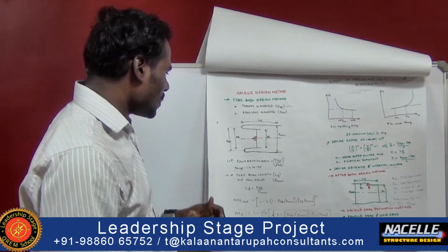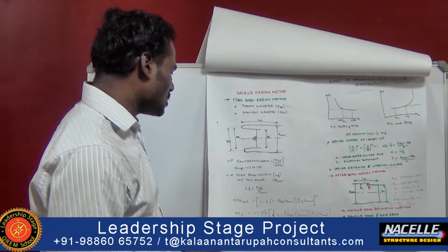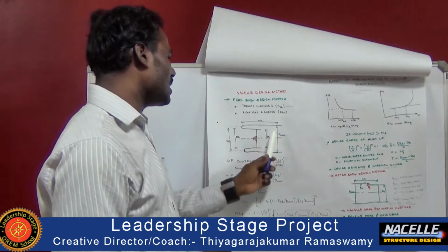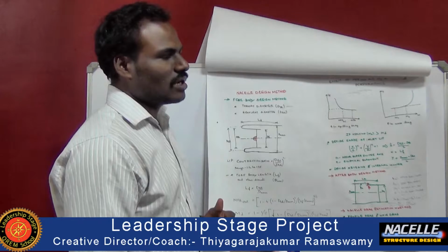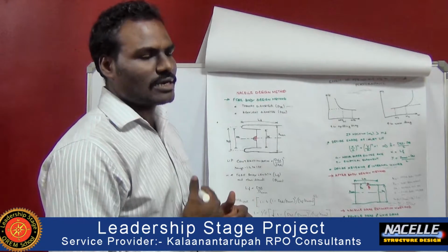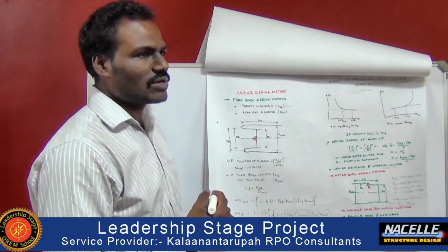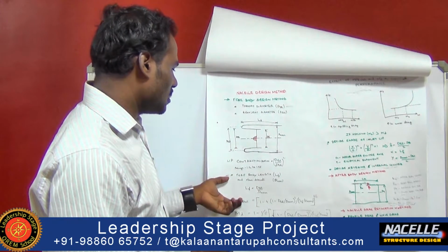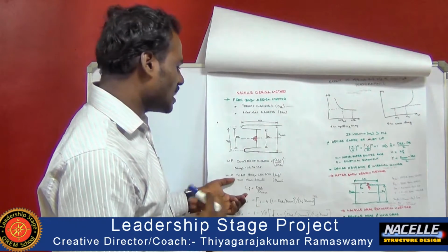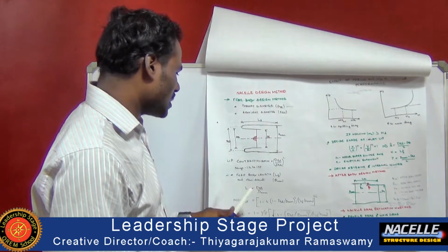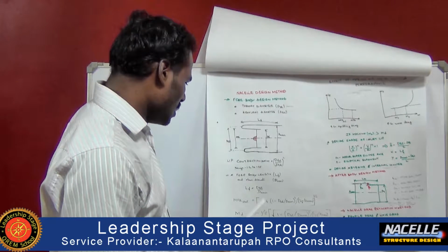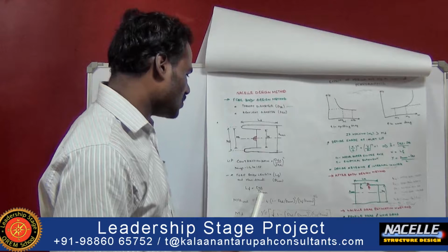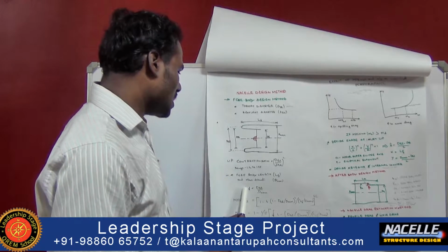Whereas for then we are going to discuss the forebody length. This is the area where we need to calculate the length in order to maintain a better drag flow, in the sense without any spillage drag. So we need to concentrate more on the length of the nacelle. Here, the forebody length is calculated using the formula, the highlighted diameter with respect to the maximum diameter, with respect to maximum width.